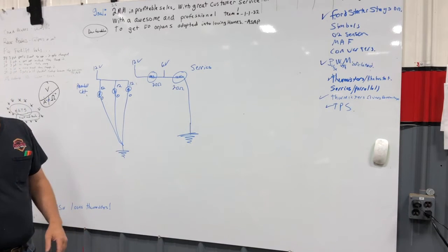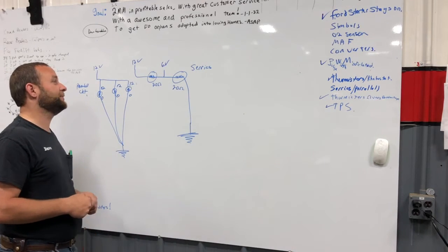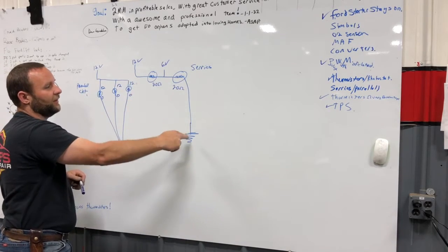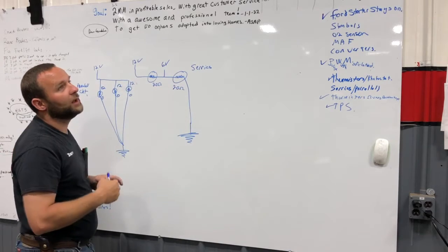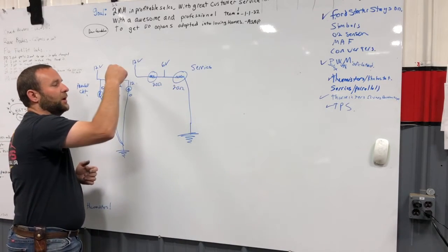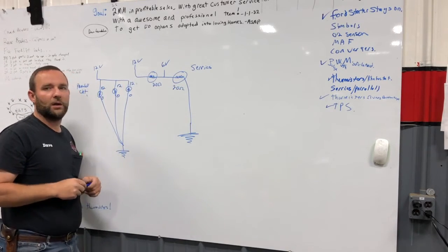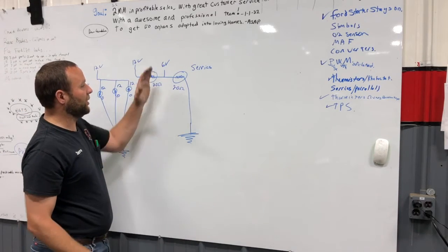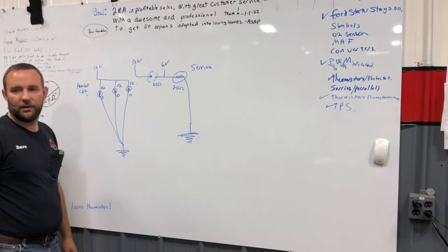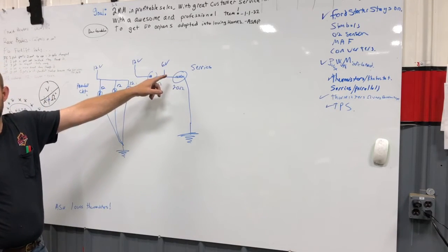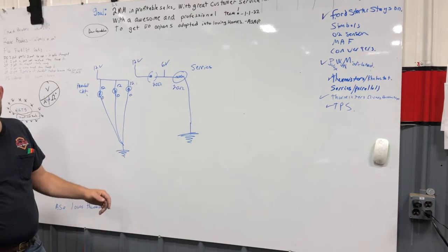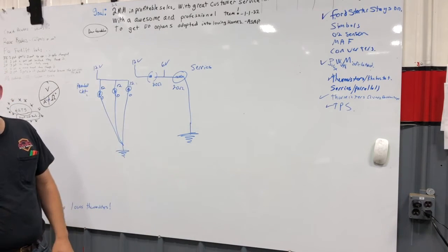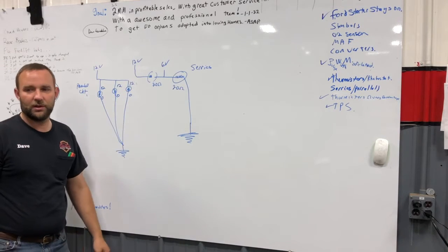The problem is, it would switch it between the two. So let's say for current to flow through here and to have resistance through here, both of these light bulbs have to be good. What happens if one of these goes bad? Both go bad. Does that one work? No, it doesn't work. So on the GM system, when they lost one cooling fan, they lost the low speed. They still had the high speed with one of them if it worked, but they would lose the low speed.